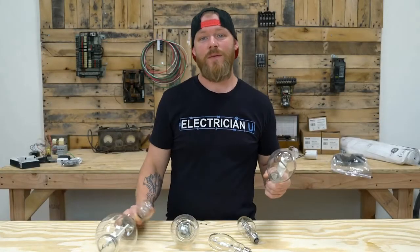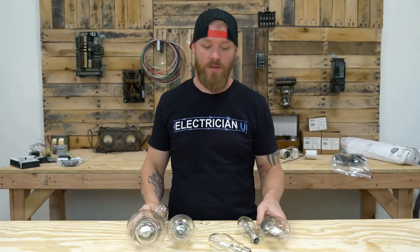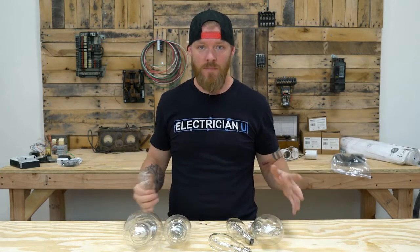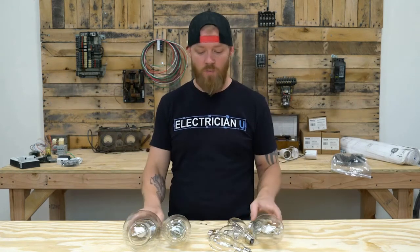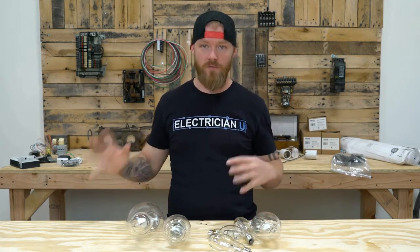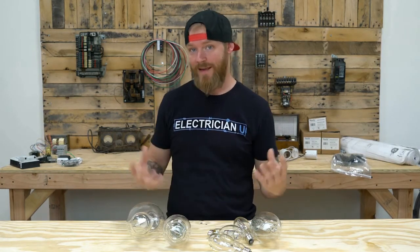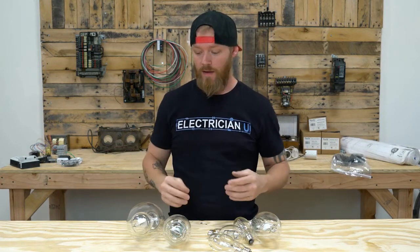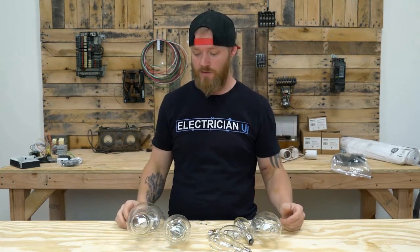All right, so the next type of lamp that we're going to talk about is the metal halide lamp. Metal halide is from the HID family. HID lighting means high intensity discharge. Essentially, these work very similarly to a fluorescent lamp. You're sending an arc through a tube. That tube has a certain gas in it that's able to produce a really high intensity arc, and through controlling the substances inside of that tube, you can control the color and the temperature of that tube.